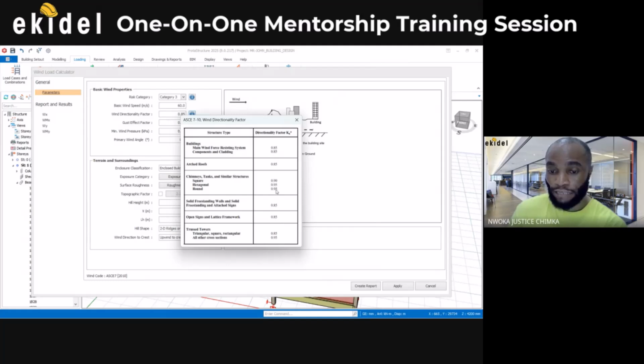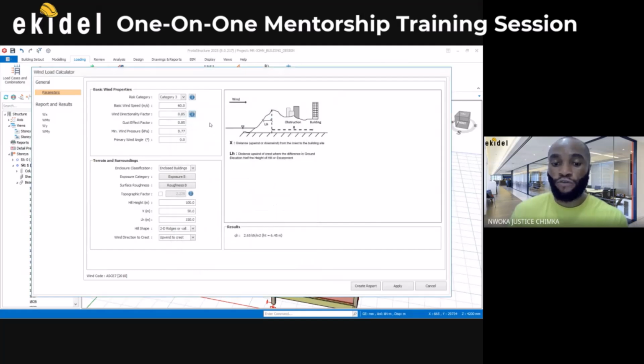That one is for chimneys, tanks, so those kinds of structures, you can pick this. But apart from that, all the rest are 0.85. You can also see triangular trusses, but for this case it falls under 0.85. So you can choose 0.85 as our factor, which is already here as the default.